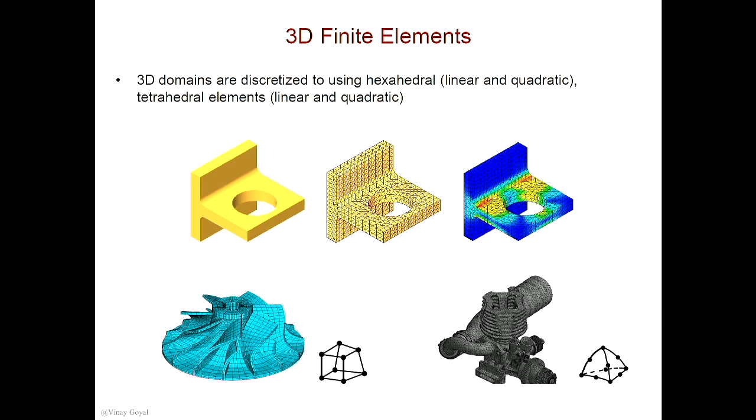With 3D finite elements, the idea is that you'll use hexahedral elements to discretize the domain. You have a CAD model. You discretize that domain. What you're really doing is discretizing the domain into elements that you can then map to standard-looking elements, which you can now solve the partial differential equation. Then you can assemble everything together, apply the loads, the boundary conditions, and then you will get the